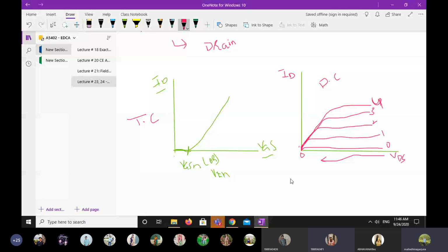Sir, I thought we will get negative current. No. How would it get negative current? If you make VDS equal to 0, you are not applying anything. Though you are applying VGS positive, the channel is created, but the VGS output is not attracting the electrons, so the current will not generate and it will become 0.